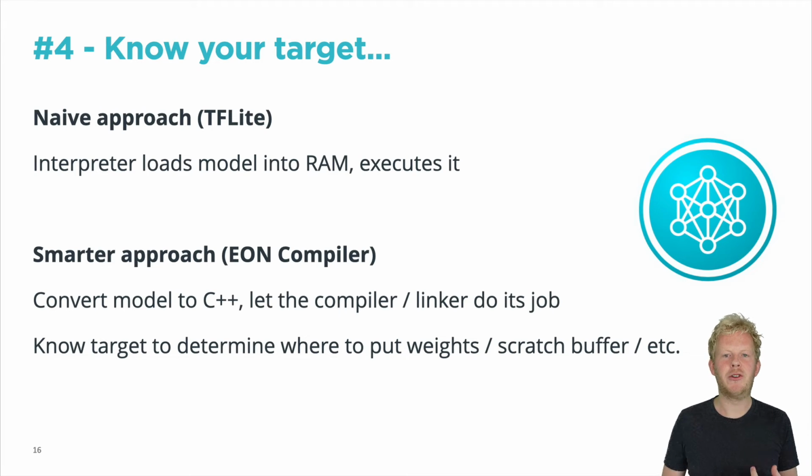So then you lose the interpreter, you lose anything that you don't use, which is really great. So very big memory savings and flash savings. And last, because of this, we have full freedom in how we put everything somewhere on your MCU. So if we know your target and we know you have fast RAM and slow RAM, we can put your weights somewhere and your scratch buffer somewhere else, etc. So be much more flexible.